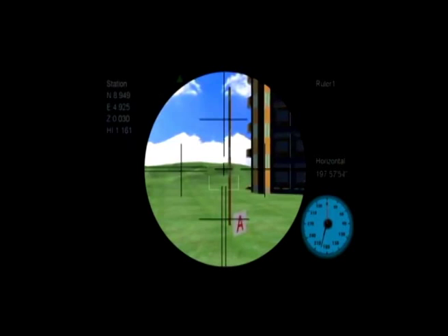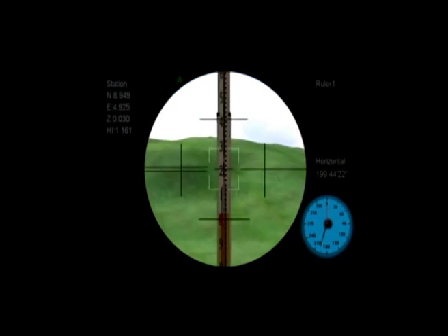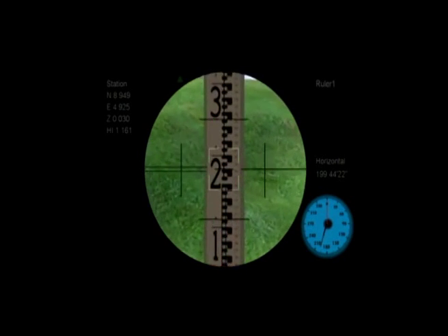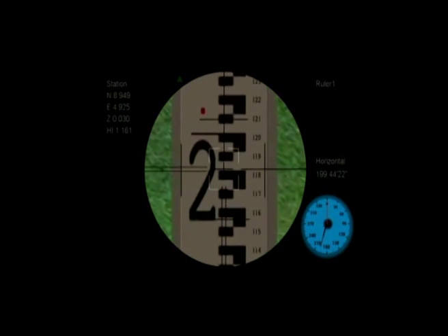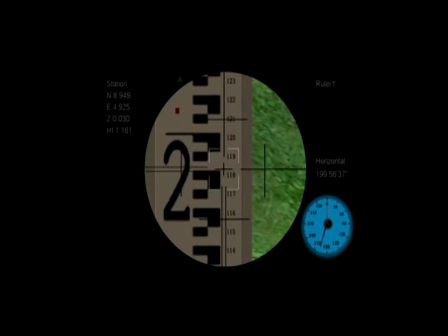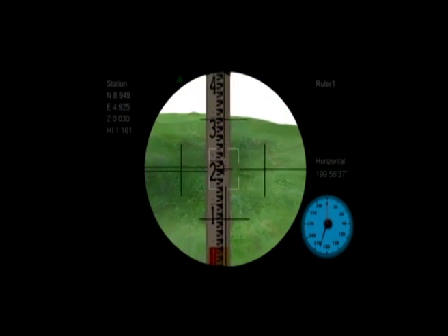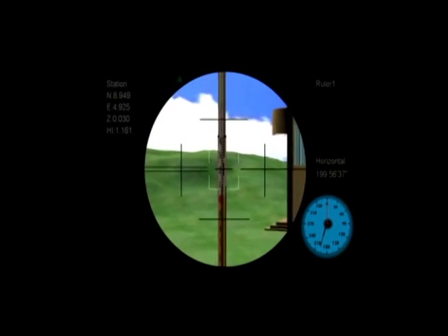The clinometer is also commonly used by foresters to obtain the percent slope of terrain. This measurement is based on the same trigonometric principles described above. Slope measurements, however, require that both the observer and the target be at a constant height above the ground. Thus, a range pole or height of measurement h stick is often used in slope measurement.